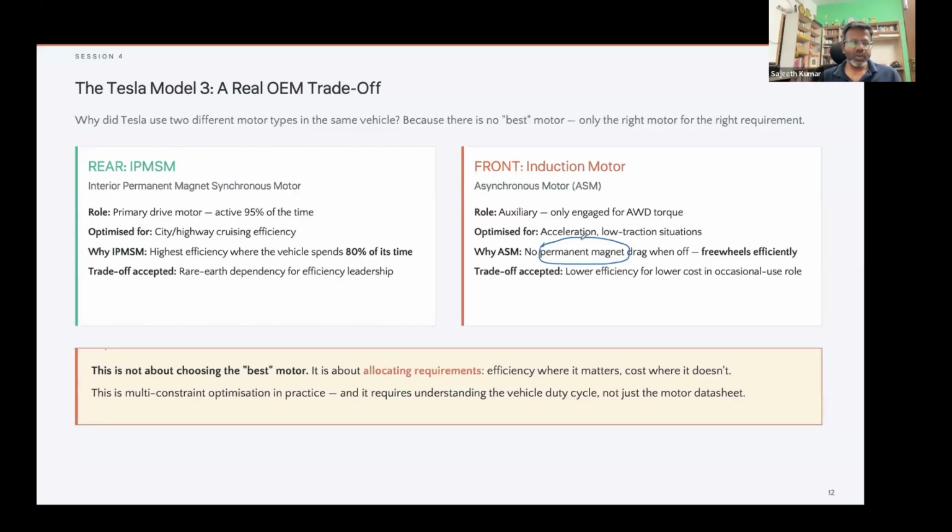Okay, cooling for EV two-wheelers. Right now, what we have done is we have gone for PCM, phase change material-based sleeves. It's a pretty new technology, and we've also gone in for chilling plates, liquid cooling. And in our case, what happens is we have an integrated power module.